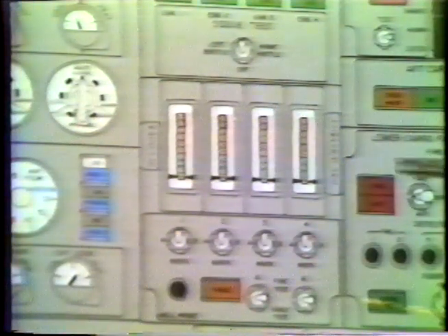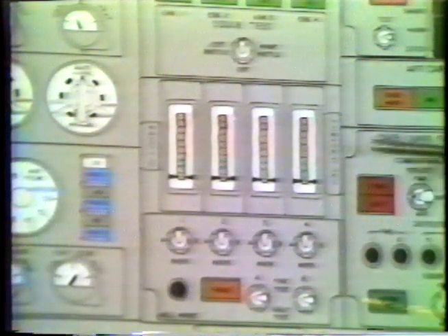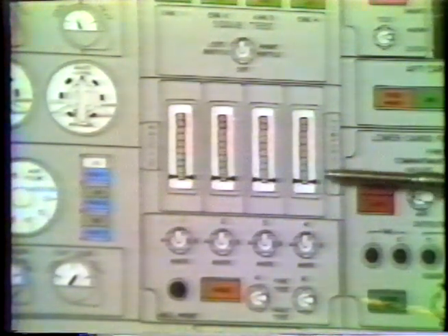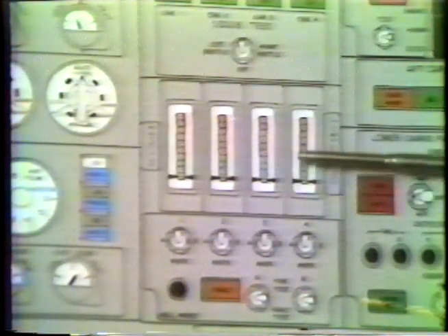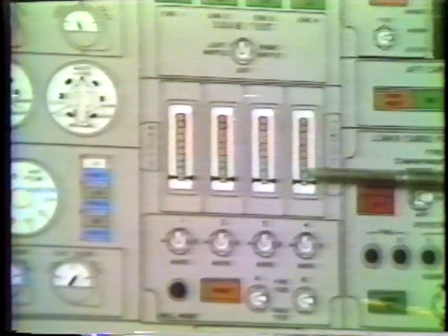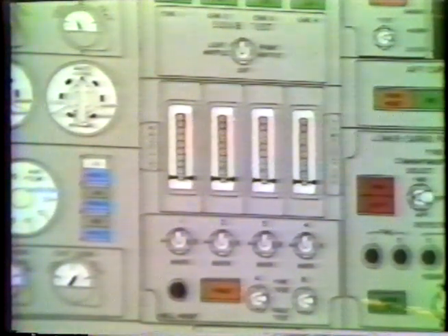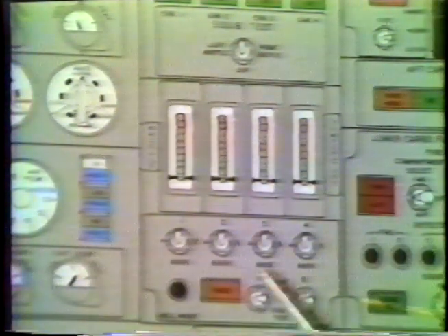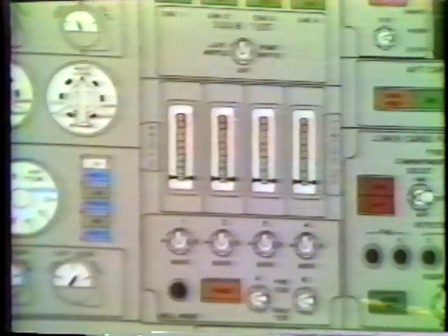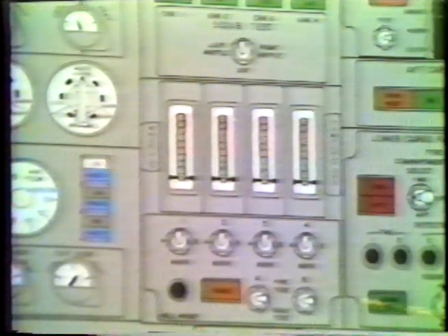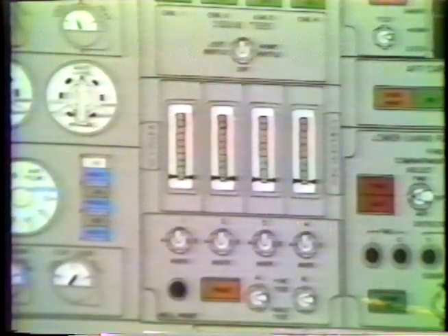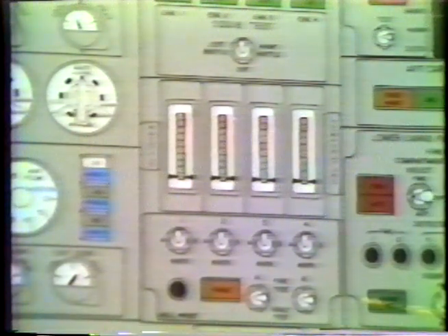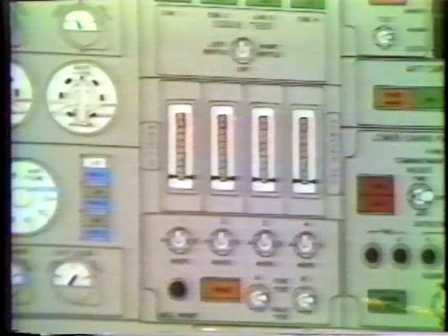Now, that's when everything's working fine. But suppose one of these pointers is inoperative. It isn't working at all. If one pointer goes up into the fire band and the other does not get to the fire band, you will get a fault light with the switches in both positions. That does not necessarily mean there's a fault that is giving you a false fire warning, but you have to go through the engine fault light procedure to determine whether you actually have a fire or a fault.